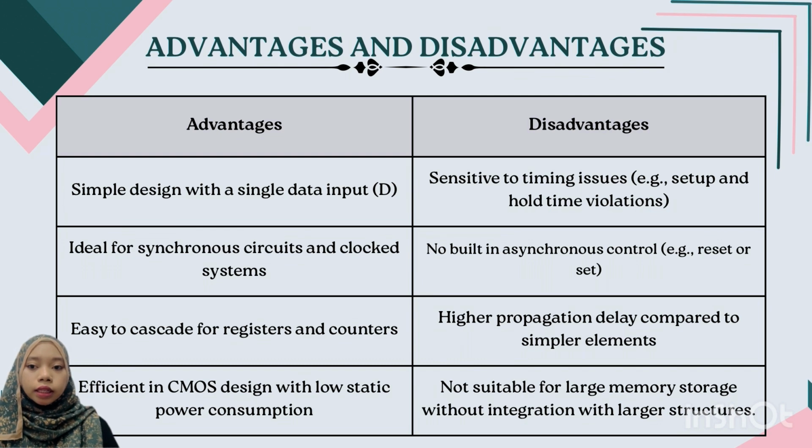Another advantage is its cascadability. The flip-flops can be connected in series to form registers and counters, which are fundamental building blocks in digital systems. Finally, when implemented with CMOS technology, the flip-flops are efficient, offering low static power consumption, which is crucial for modern power-sensitive applications. However, there are some disadvantages to consider.